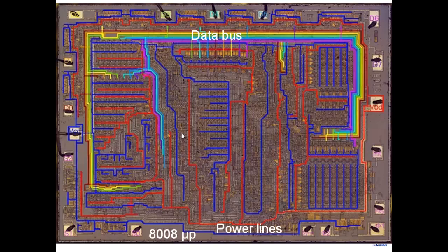So look at how VDD goes here. These are the power lines. Can you see the power lines? VDD starts from here. Note how VDD is distributed. It doesn't show all of them, but it's distributed all over the chip. And this is the ground, the blue one here. It has to go everywhere. So you have to design your power distribution system, a power distribution system to 6,000 homes, as it were, since there are 6,000 transistors, and a ground also to all of them.